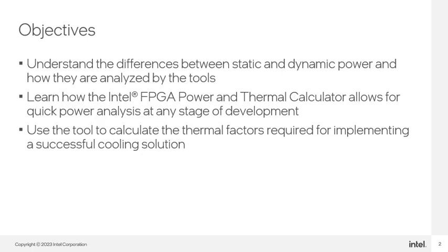You'll also see how the tool can be used to calculate the thermal factors necessary for implementing a successful cooling solution for your design. The PTC takes into account the unique multi-die design of Intel Stratix 10 and Intel Agilex devices to provide a complete solution for power and thermal analysis.